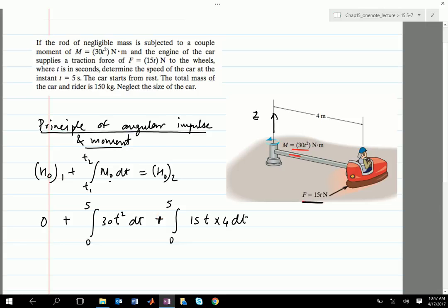Now, if I had changed this into a force which was opposing motion, a friction force for example, it would have been in the direction exactly opposite to that force, in which case the moment would be in the negative direction. So you have to put a negative there. Changing that sign is going to be very important. That's why you've got to think about a coordinate axis before you solve this problem. Otherwise you can mess up the sign, which will mess up your answers.